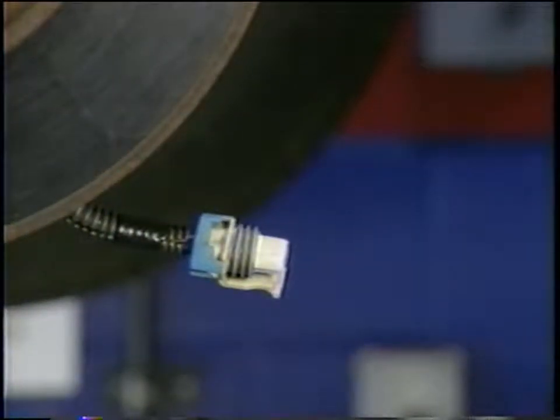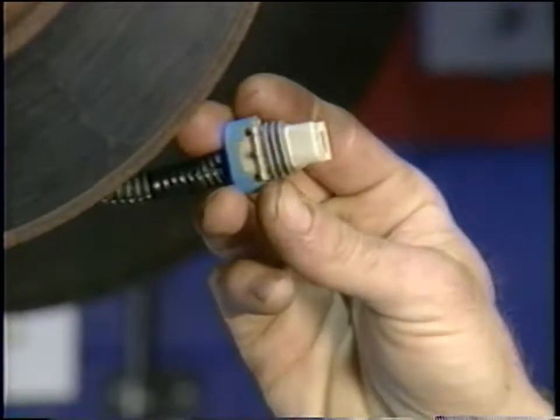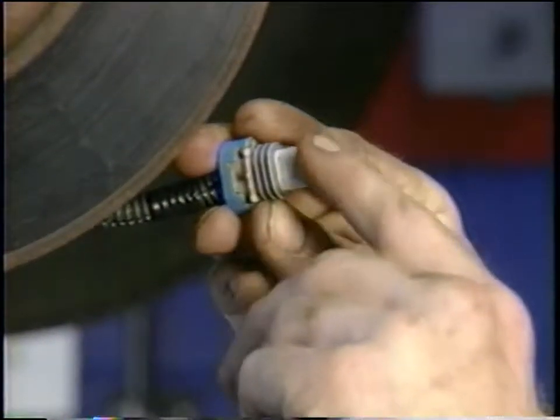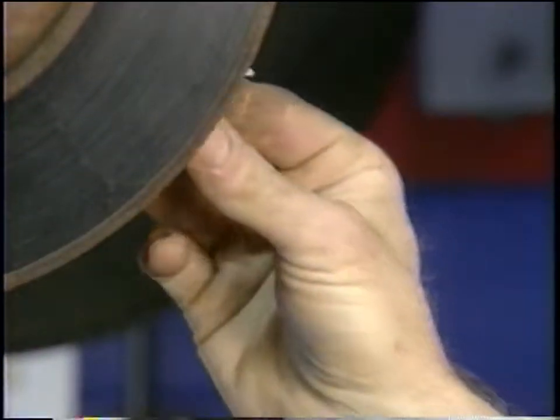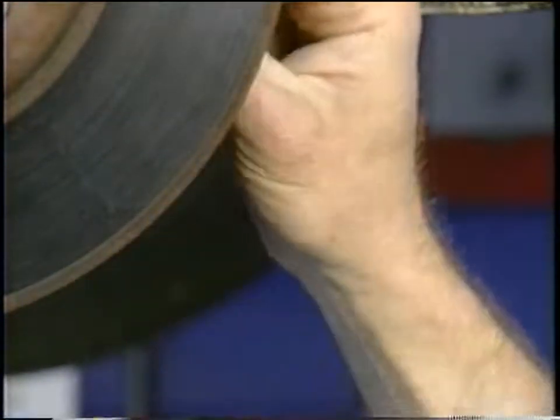Before connecting the wheel speed sensor's wiring harness, apply dielectric grease to the connector terminals to protect against corrosion. Align the connector, then snap it together and make sure it's locked in place. Also, check to see that the wiring is properly supported and positioned away from moving parts or suspension components that may damage it.